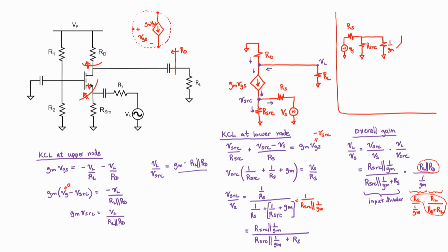We can then treat the transistor as a voltage amplifier. The gain will be given by this expression right here, positive Rd divided by 1 over Gm. So you can think of it as two resistances, the resistance up here divided by the resistance there. Finally, we have our output impedance, RD, and our load. This is the equivalent circuit that I'll use when we work the next examples.